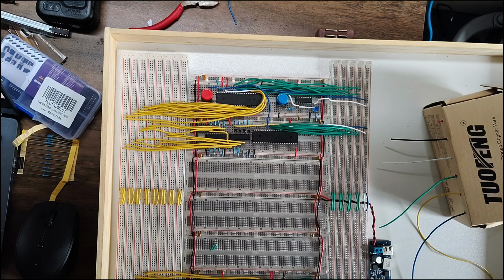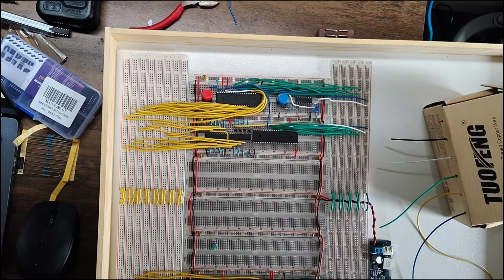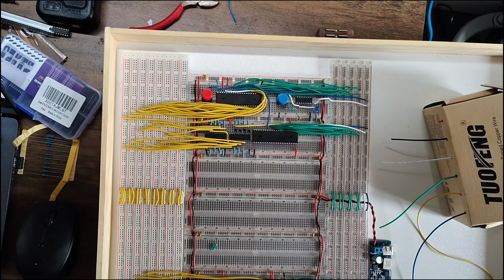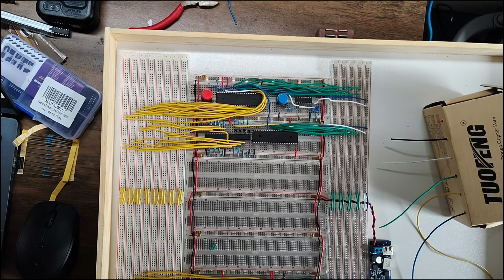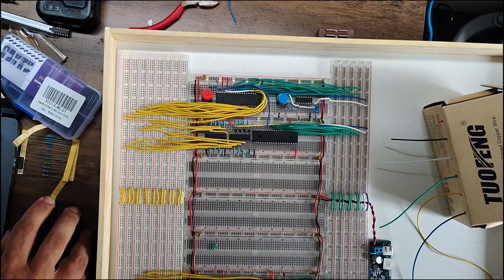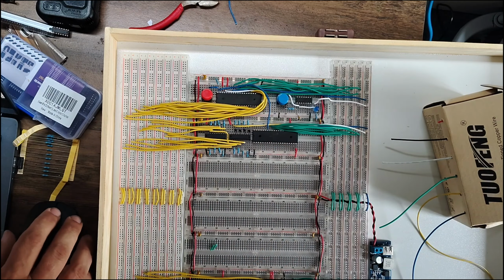The one thing we do have to do is, if you remember, we set up all this address logic here to make sure that only addresses starting with 600 get through. But the last byte of the address, 0 through F, is going to tell us what instruction we want this thing to actually do.